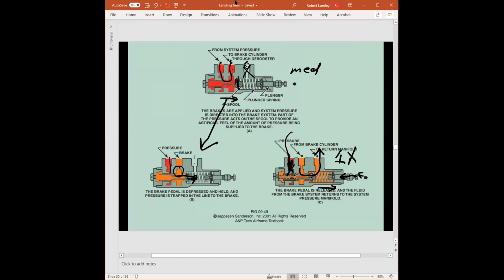Now, as said, from the power brake valve, it goes through the anti-skid control valve. Now, the anti-skid control valve, sorry to say, is discussed more in detail with airframe 2. But all we need to know about it is if the control box senses, hey, a wheel is skidding, what does it do?